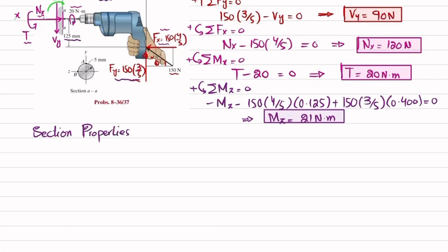First we will find the area. The area of this circular twist drill will be equal to pi r squared, and r is given as 5 millimeter, which is 0.005 whole squared. So this will be equal to 25 multiplied by pi into 10 raised to power minus 6, and the unit will be meter squared.